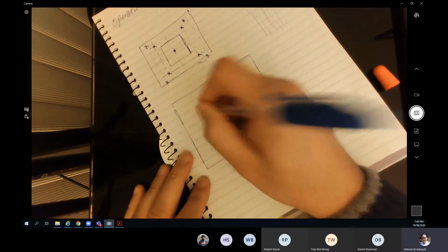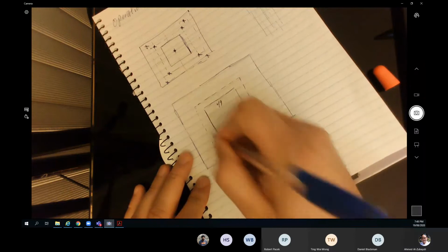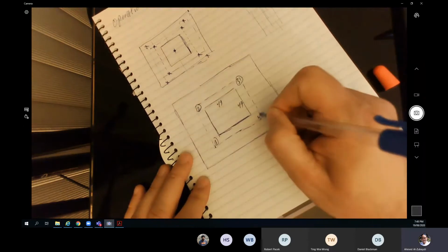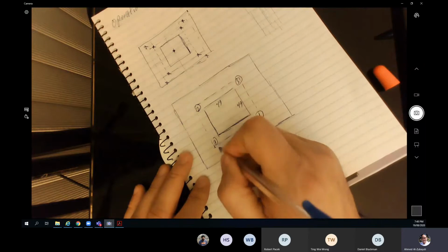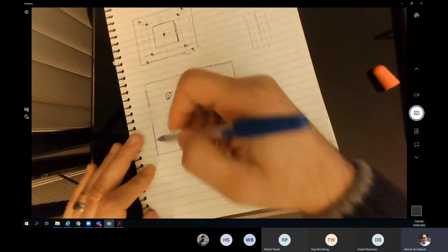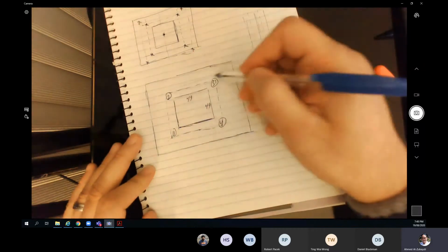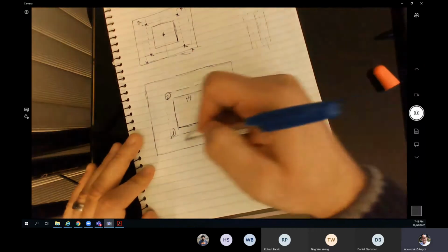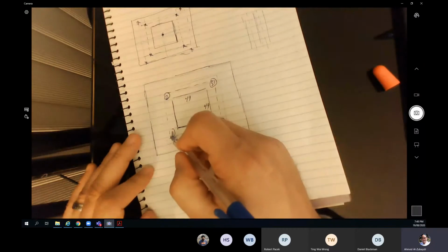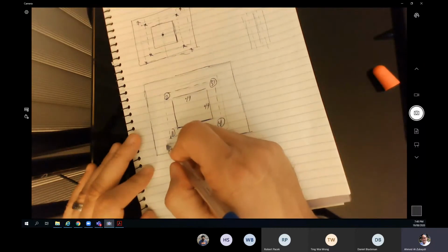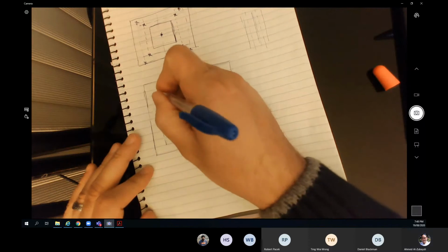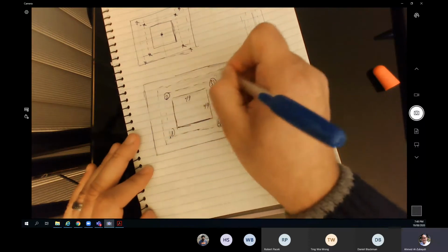At the beginning, we're going to move from 1 to 2 to 3 to 4 to 1. So we're removing everything around the part by the width of 12 millimeters. Then from here, I need to move to a new location, which is going to be this larger square.